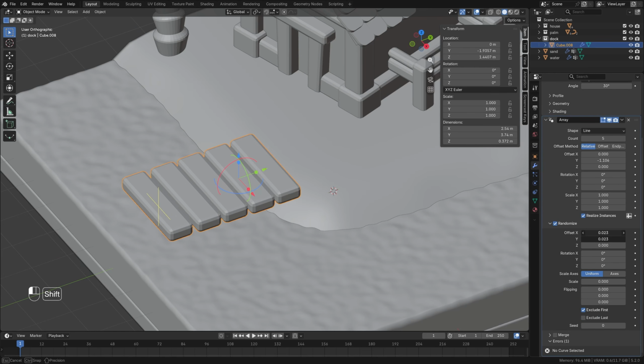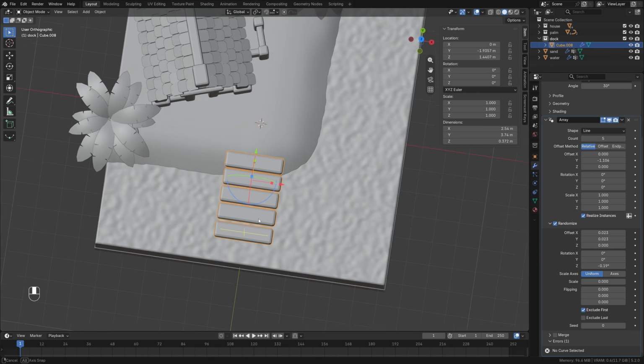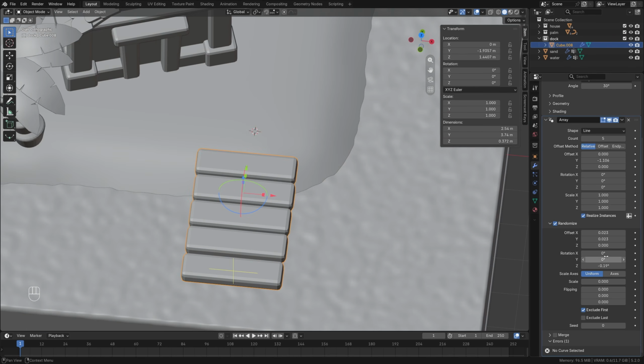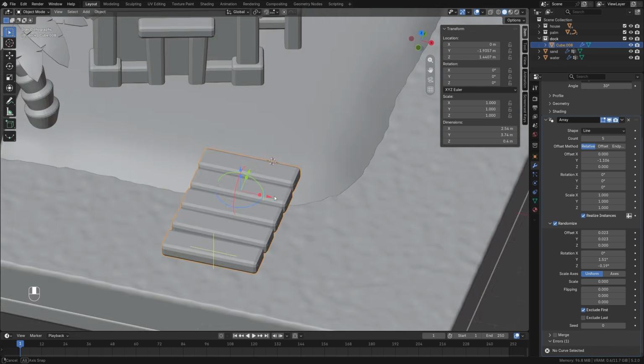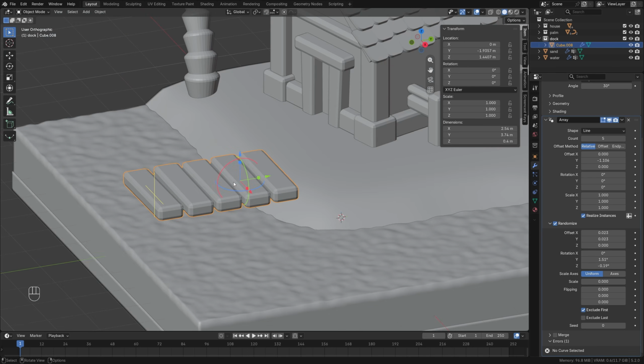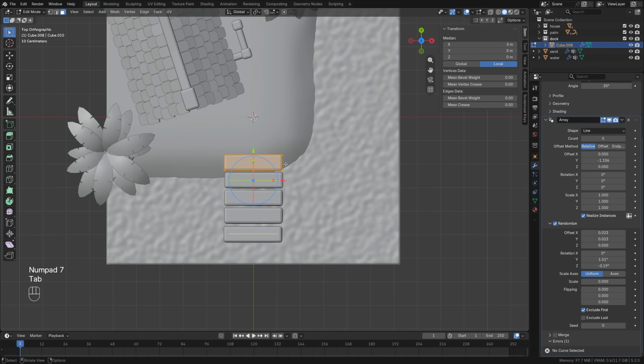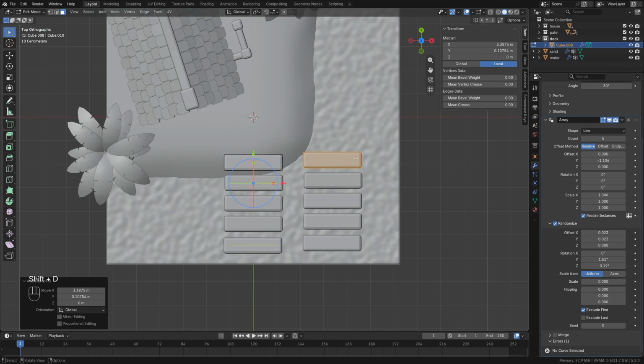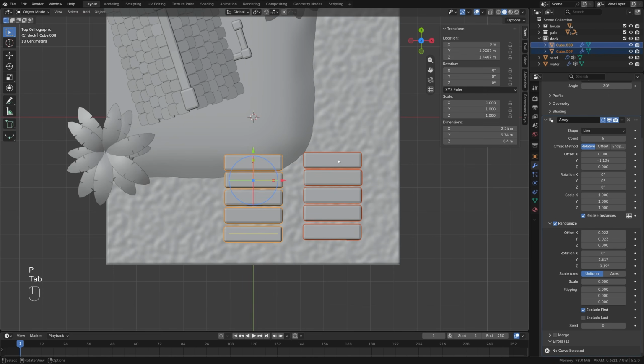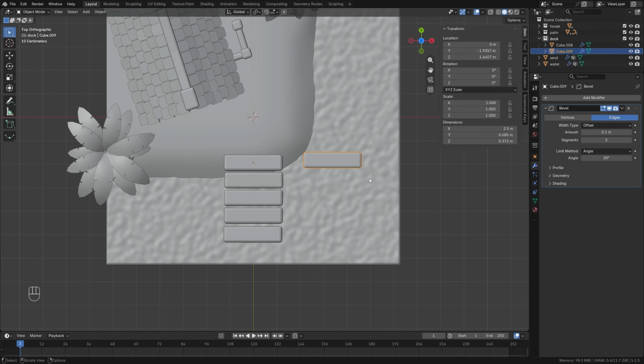Offset along 2 axes can be adjusted a little. Rotation along the Z-axis make a small one. That is, essentially, the bridge should be straight, but at the same time not completely, so that it was visible a little how these boards duplicate. After this, we switch to top view in edit mode, duplicate our bridge. We press P, selection, move all this into a separate object. We return to object mode, and already for this bridge, the array modifier we delete.